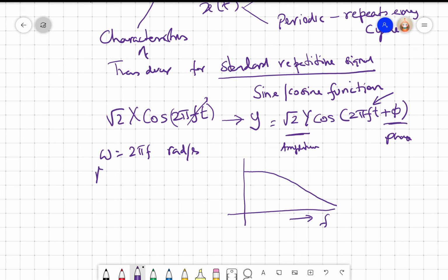We call this frequency response characteristics, right? Because this is amplitude. It could be output amplitude by input amplitude, or simply keep the input amplitude constant and find out what happens to the output amplitude. Now we already said that we will have to put a particular cutoff frequency Fc.